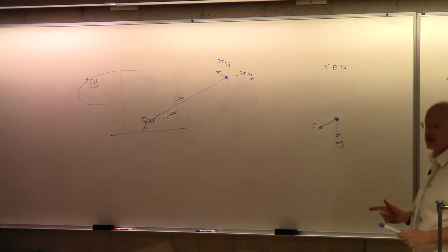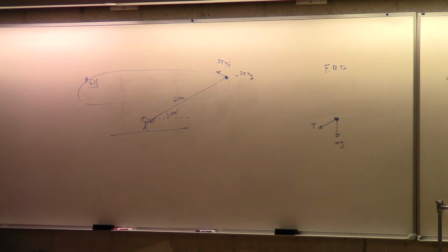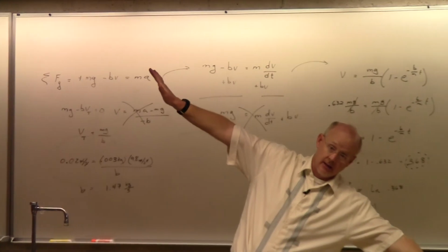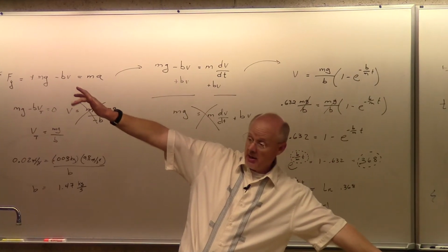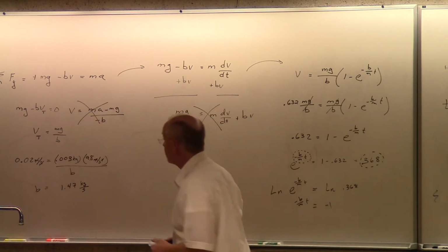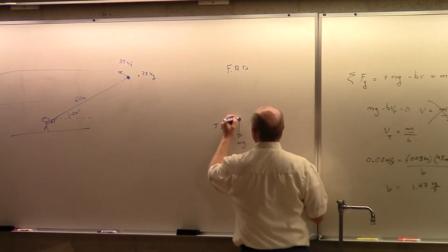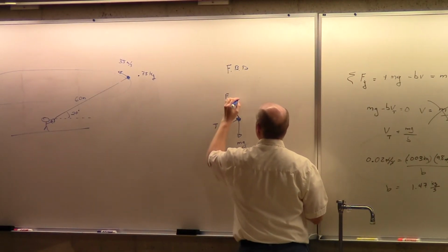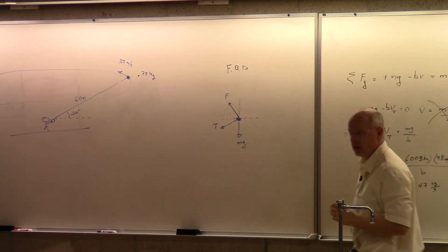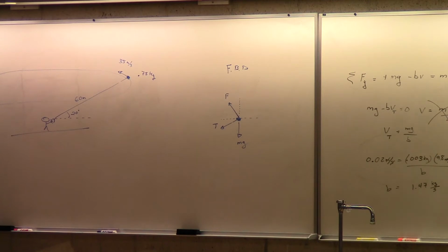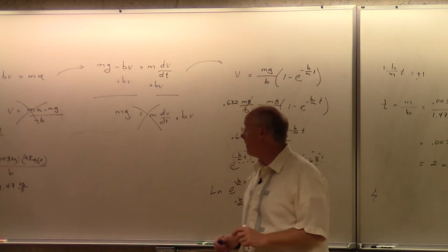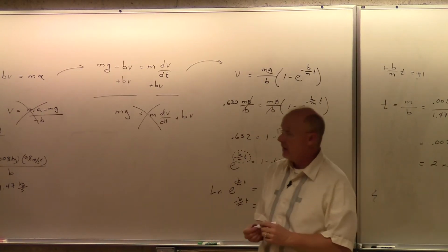Now, their picture is much nicer than mine. They make it pretty clear that the control wire is connected to the tip of the wing. So this airplane is flying like this. So which way is the aerodynamic lift? Yeah, perpendicular to the wings. So for the aerodynamic lift, I'll put a little F here, and put maybe some horizontal and vertical lines in here so you can see it. But the lift, if you will, is angled slightly in.